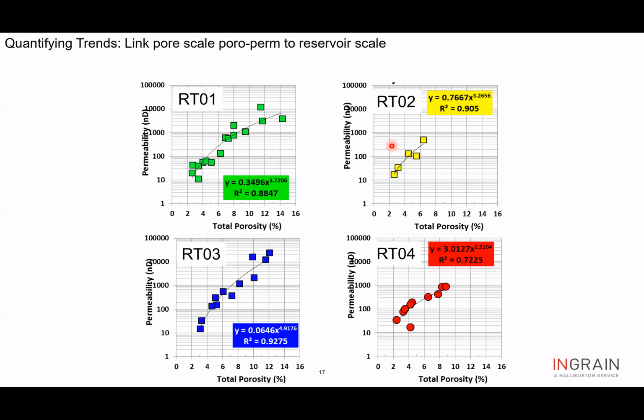So once these different rock types are identified, and the porosities for all these different sections are estimated or measured from this digital rock, then those are converted using a lattice Boltzmann method for permeability. So now for all these different rock types you have different permeabilities, and then you can upscale back to your facies level from the whole core scale.